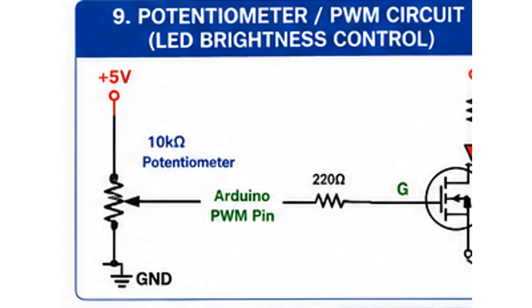Because of the insulating oxide under the gate, MOSFETs have extremely high input impedance. BJTs have much lower input impedance. MOSFETs are outstanding for switching applications, especially power switching, because they can be driven with simple logic levels and dissipate little power when fully on or fully off.